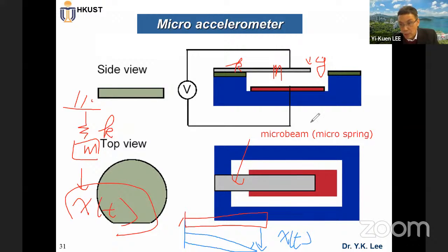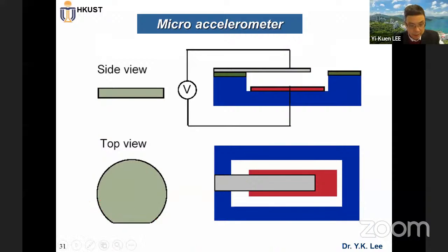So in this case, input G acceleration, output capacitance change. With two pairs of electrodes, once it vibrates, we input acceleration, output capacitance, and then you can measure the acceleration. So this is a very basic thing that shows you how these devices work. Do you understand? Without going into much more detail, at least this is a very simple way.